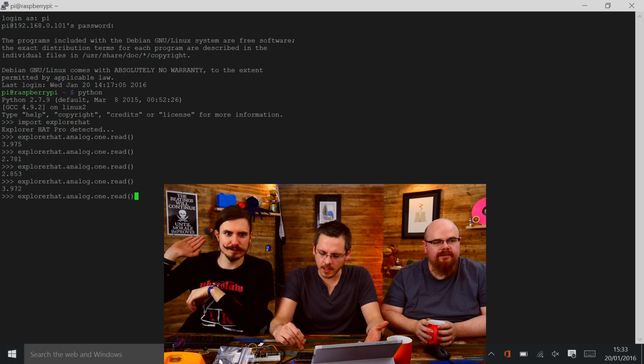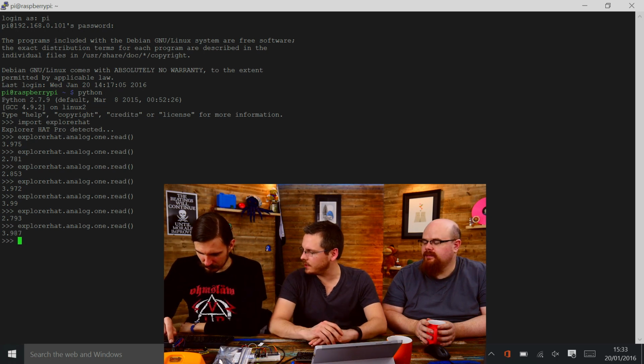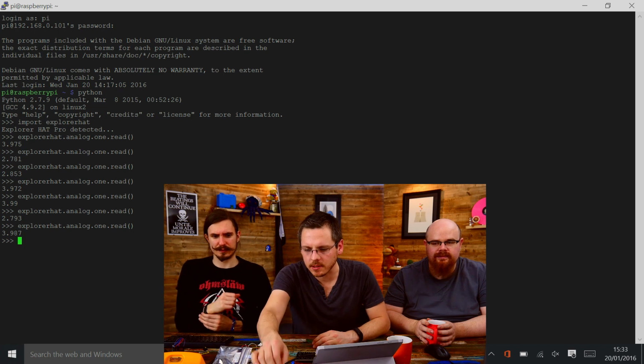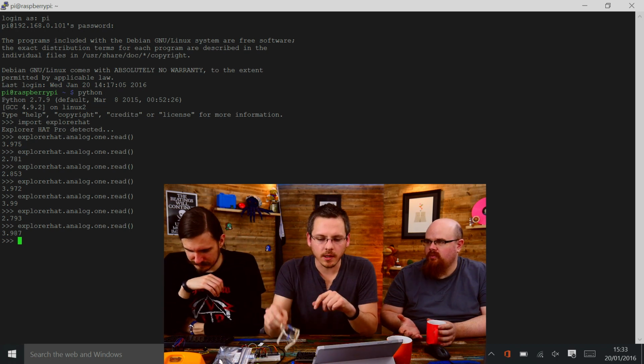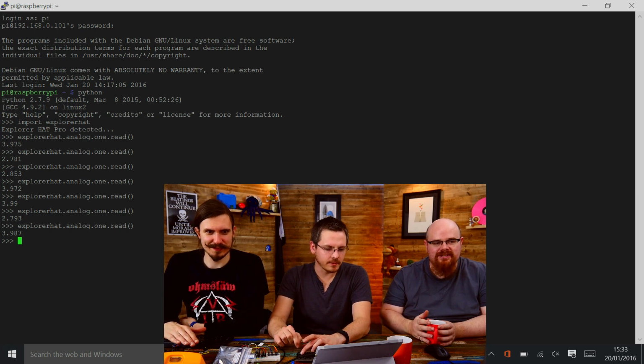So basically, as much light as is entering that sensor is mapped. I have no idea what this light sensor is, so I picked a fairly arbitrary 10K resistor value. I think I've got 22k on there. I had 10k. Okay. So it'd be a bit unbalanced. I've got some 10k resistors here. So you were sampling about 1 hertz there. You were taking a sample every second. Yeah, something like that. Just for comparison.